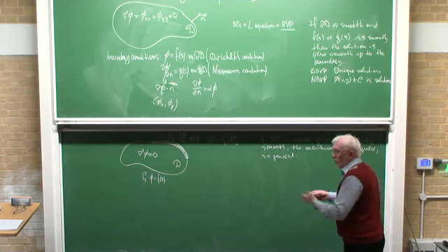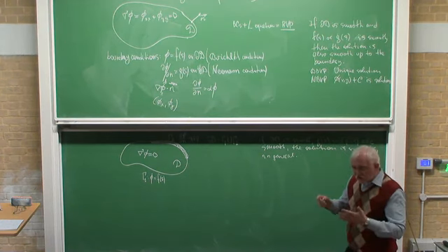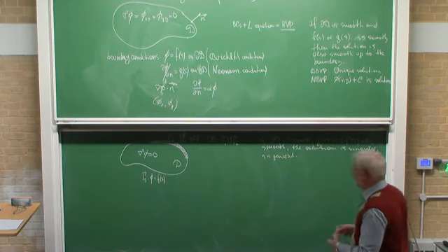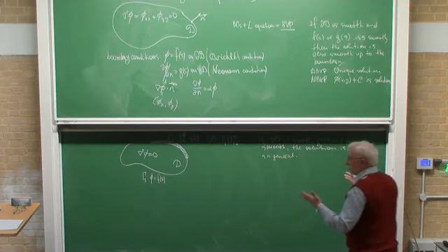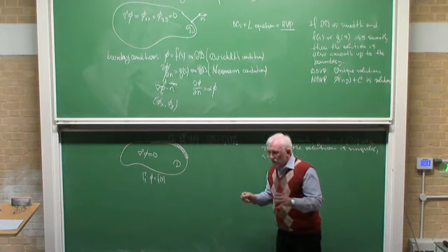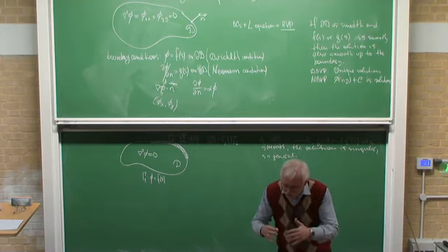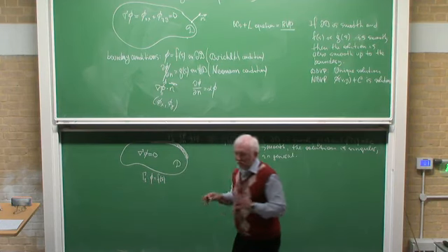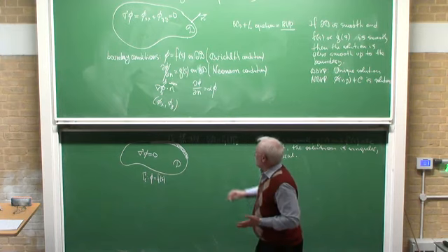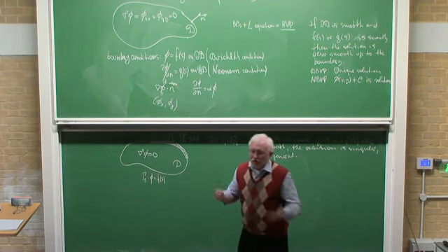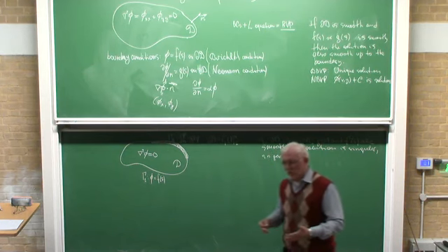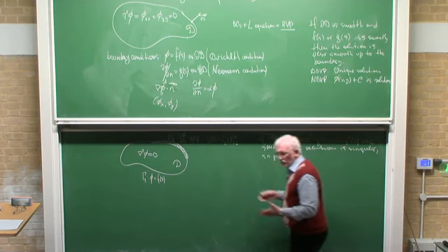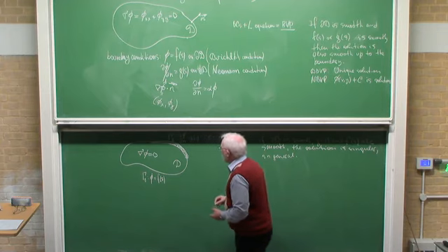Because you need to incorporate that singularity, and you need to know that singularity. Whatever may happen, if you do not account for that singularity and you reduce the mesh, you approach the point at which the boundary condition changes type, then your solution just blows up. So it diverges when you reduce the size.